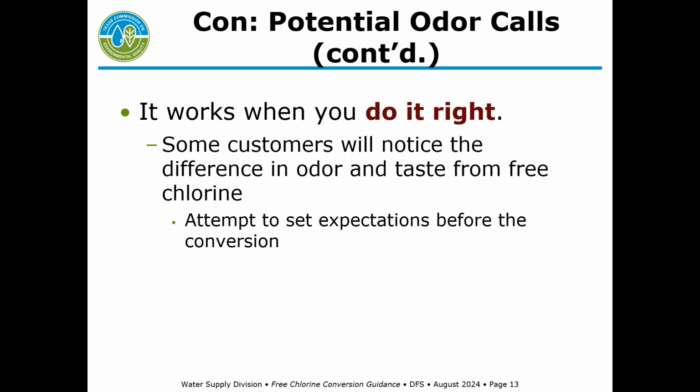Some other potential odor calls: the customers will probably notice a difference in taste or odor, just from the change from chloramines to free chlorine. It's a good idea before you do the chlorine conversion just to notify your customers: hey, this is what we're doing. You may notice a change in taste, but we're not adding so much chlorine that it's going to burn your skin or anything. You may smell it, but just try to set their expectations ahead of time.